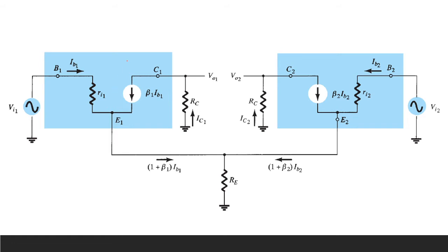The equivalent of a transistor when we use the RE model is this: a constant current source with a resistance here, Rin, which is actually equal to beta Re. So, this is beta 1 Re1. This is beta 2. No, not this one. This is beta 2 Re2. Okay, so that's our analysis.